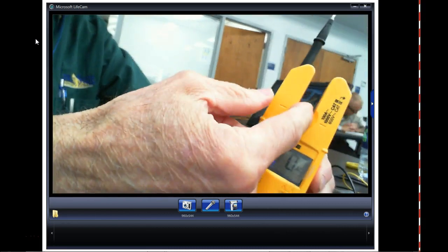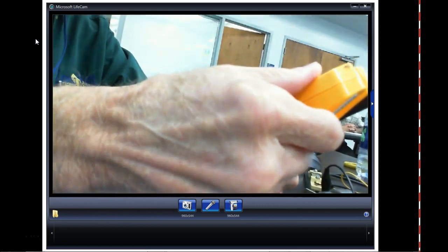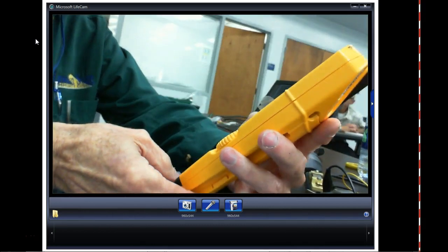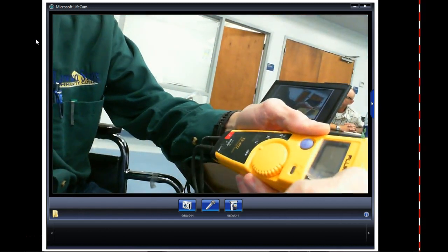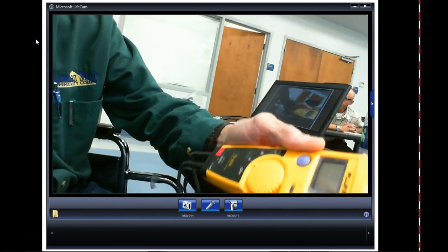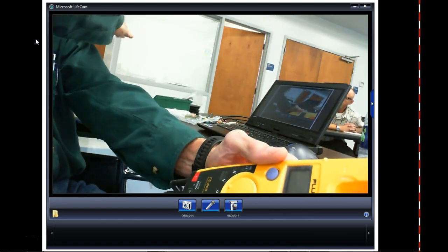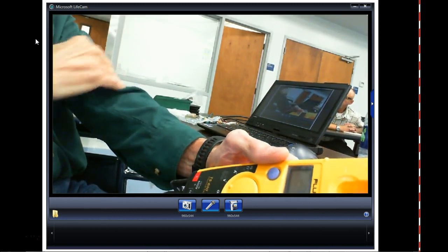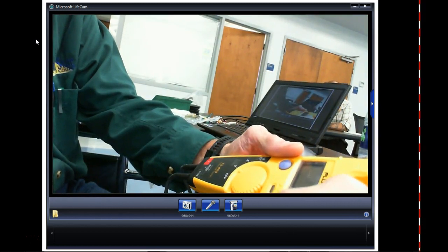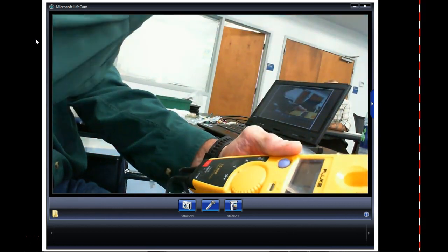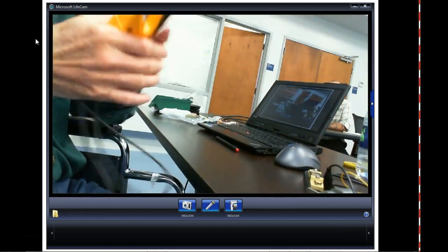But this is still a compound ammeter, so you put it in here. It doesn't tell me the ranges, we'd have to look it up. But this is Cat 4 at 600 volts, Cat 3 up to 1,000 volts. Normally they'll double rate the meters, but they drop back to the next lower voltage for the higher Cat rating.